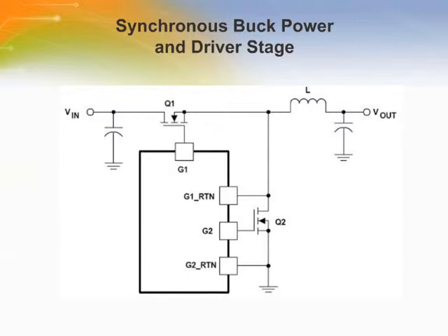Driving the gate of control MOSFET Q1 and synchronous MOSFET Q2 with one voltage level versus another requires careful consideration in order to weigh the benefits of one gate source voltage versus another. The RDS-on versus gate drive voltage and gate drive voltage versus gate charge curves for each MOSFET must be carefully looked at.